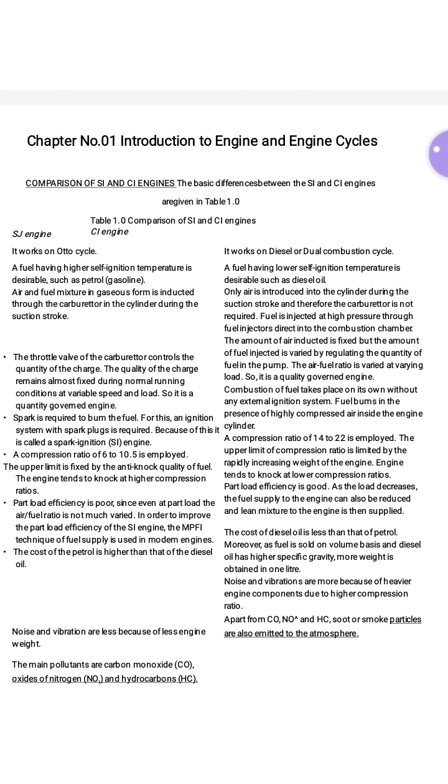In a diesel engine, as per the requirement, the quantity of fuel may be increased or decreased, while the quantity of air remains the same. As the quantity of fuel changes, the quality of the mixture inside the engine cylinder gets changed.